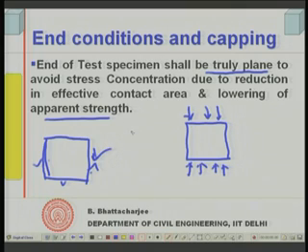Of course, in case of cylinders, we cast them vertically. So, load is also applied onto the finished surface. So, sometimes capping may be necessary, you might put capping in order to take care of the variation due to the non-planarity of the surfaces. Even otherwise, people have seen during research what happens if you put some sort of capping material. Now, this helps us in understanding the behavior, also standardizing our specimen, right.